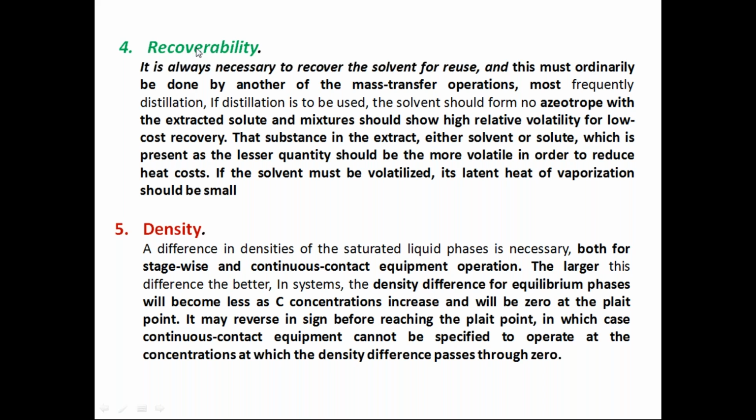So to recover the solvent, distillation is used. If distillation is to be used, the solvent should form no azeotrope with the extracted solute. So whatever solvent you are adding should not form an azeotrope with the solute. If it is forming an azeotrope, then again the separation is very difficult. So mixtures should show high relative volatility for low cost recovery.